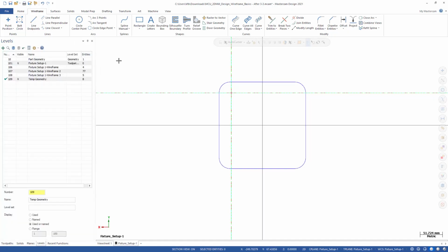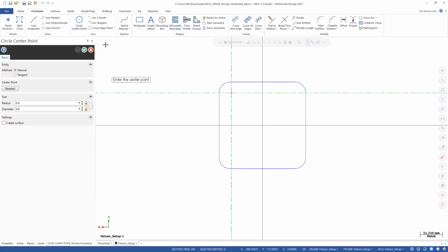While we're here, let's briefly explore the circle mode. The circle tool allows me to create a circle by simply clicking and then placing. And then I can put in whatever value I want here. The radius is 25. Obviously, the diameter changes that to 50. You can also do math in these fields. So for example, if we knew that this was 2 inches, I could type in 2IN. It automatically converts it to millimeters for me.